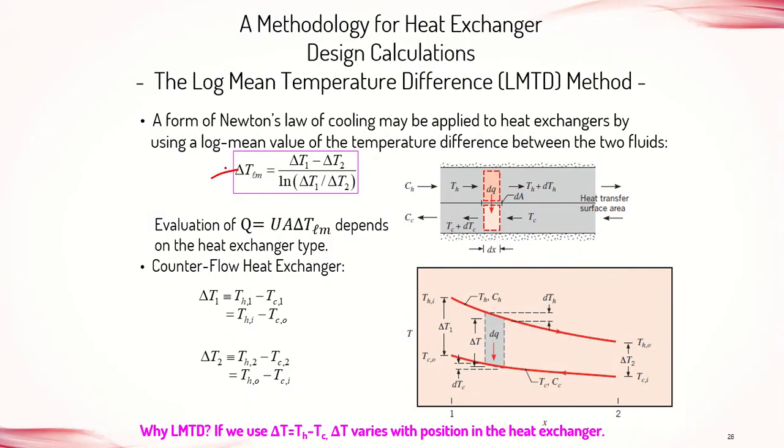The log mean temperature difference is represented by delta T1 minus delta T2 over ln of delta T1 over delta T2. So what is delta T1?